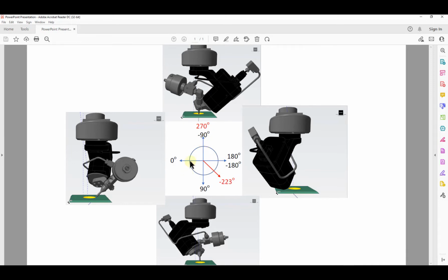So generally, you want to try to position it such that you are pointing to the right, which should give you a positive 180, and then do your inside cuts in the clockwise direction. In similar fashion on an outside cut, if we're doing an outside bevel on this part, we'd want to have it on this right edge of that part, which again should put us pointing towards that positive 180, and then work clockwise around that outside cut.